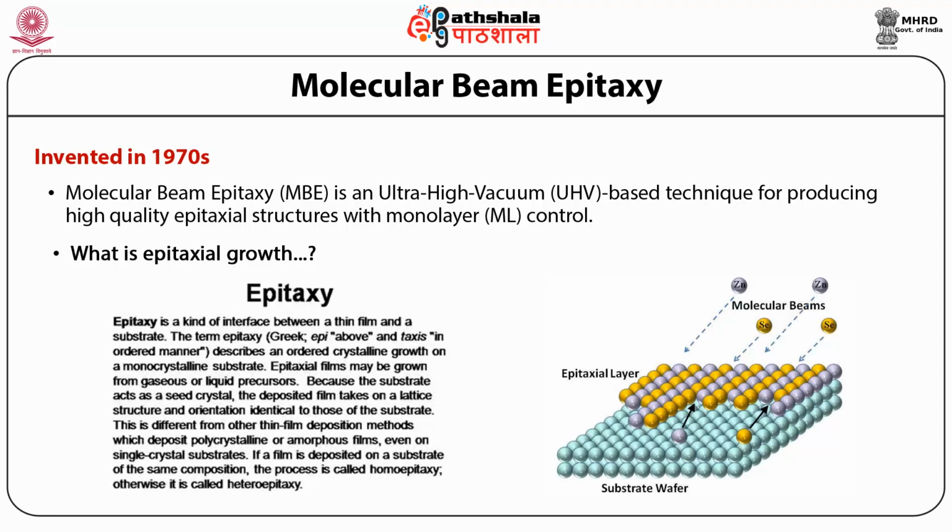Epitaxial films may be grown from gaseous or liquid precursors. Because the substrate, as you can see in this figure, acts as a seed crystal, the deposited film takes on a lattice structure and orientation identical to those of the substrate.